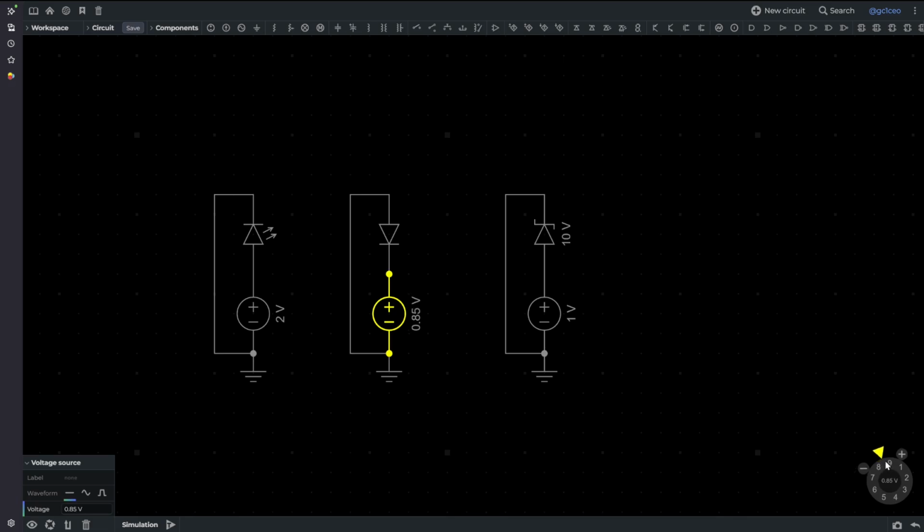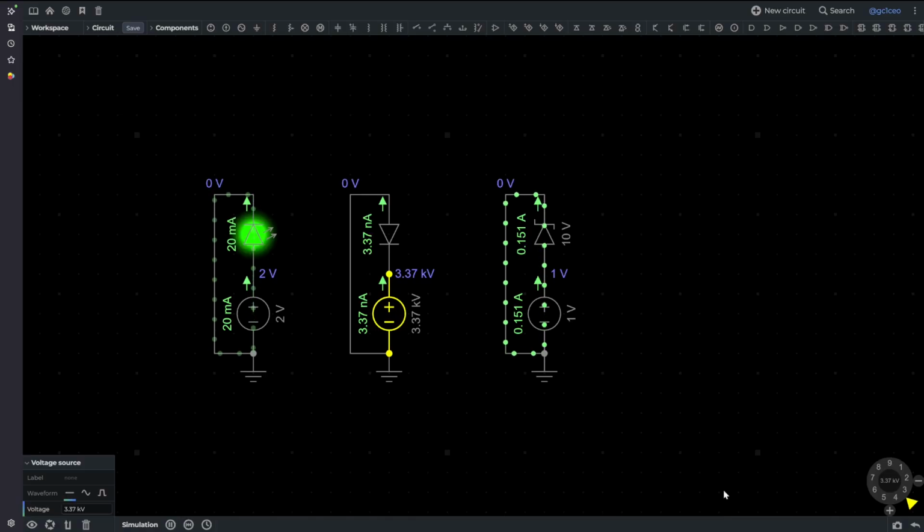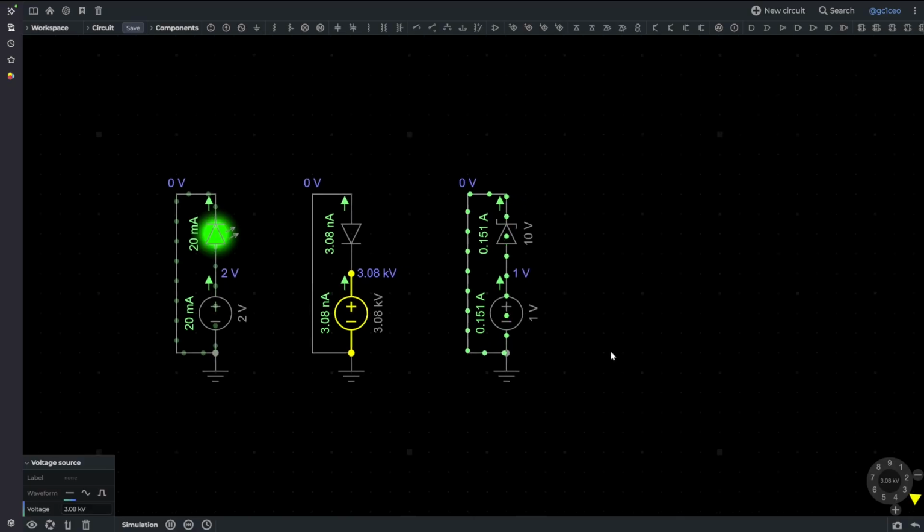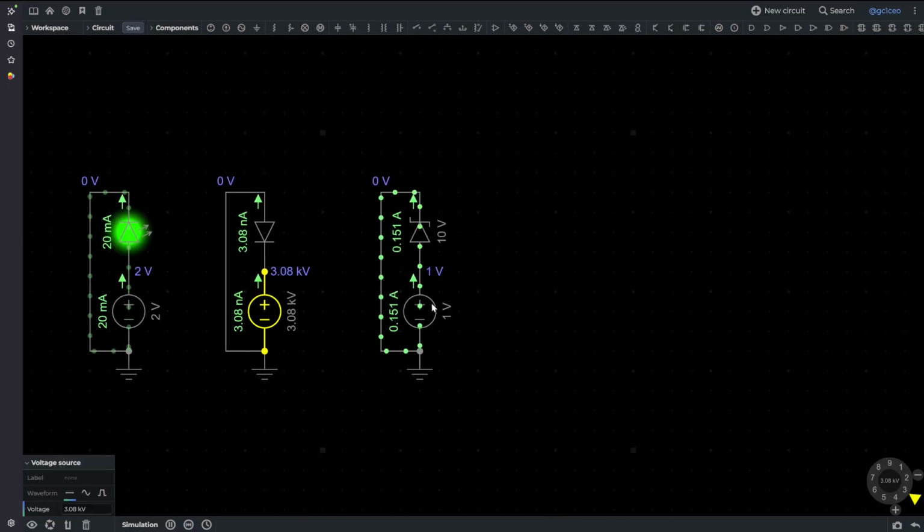Let's bring it up. I don't know what the breakdown voltage would be, but we're getting into the kilovolts and nothing's happening. Not saying any numbers. Oh, wait, whoops. Try this again. Yeah, it's just not working because it's in reverse. Even at the higher, this should be a completely, utterly out of control number. All right, well, then let's look at a Zener.